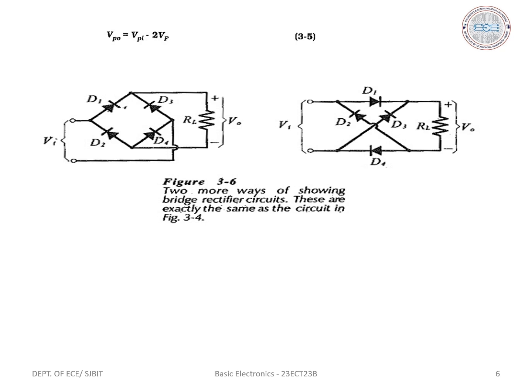During the negative half cycle of the AC input, point B is positive with respect to point A. Hence, diodes D3 and D4 are forward biased while D1 and D2 are reverse biased. Hence, the current flows through the path in which diodes D3 and D4 are connected.